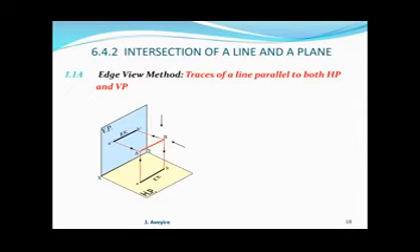Now for corresponding projections, so that we see the relationship: if you take the front view and draw lines vertically downwards to hit the XY line, and then extend them to the top view, the lines that we have here prove that the projection is right.